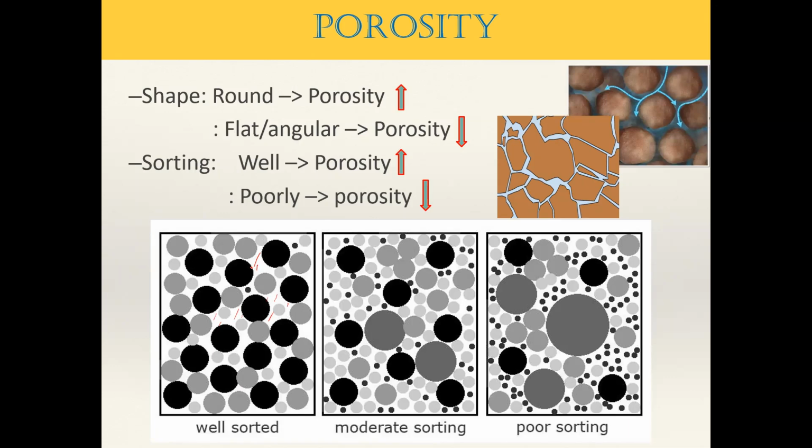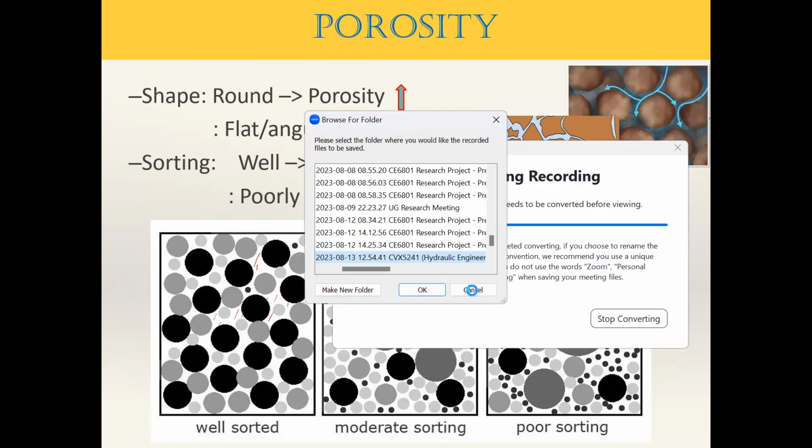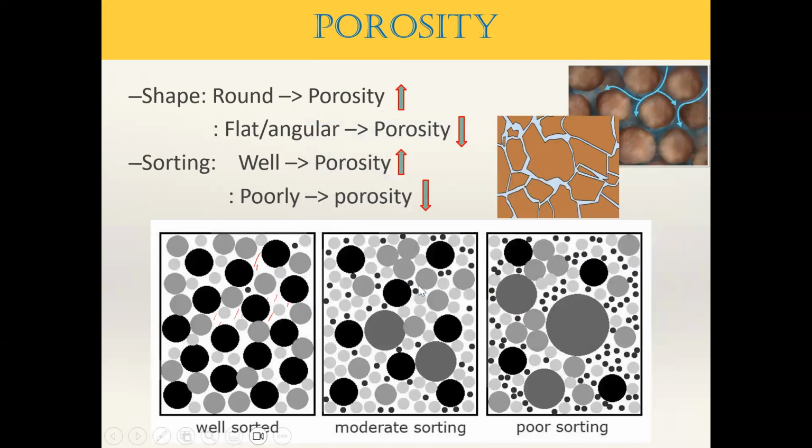You will find that in that case, the porosity you calculate becomes independent of the size of the particle. If they are round and the same size, the porosity becomes independent of the particle size. But in general, you don't find exactly the same particle size and round shape, right? Because of that, the shape of the particle also affects the porosity.